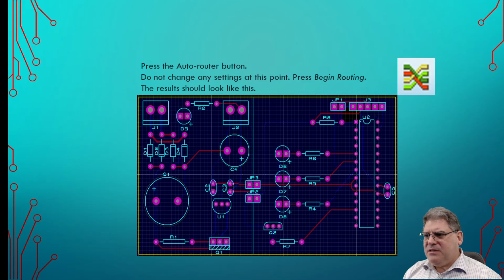Notice though that it's sloppy. I mean, no auto router does a perfect job. But silly things like why would Proteus want to do this? I mean, you're already here. Why not go through the pin? Part of it is, I'd like to give it credit and say that it wants to do a star point for the power. It doesn't want to run the power across a pin, which is a really bad idea to start with, but I don't know that it's that smart.